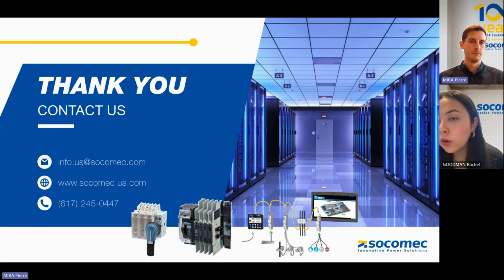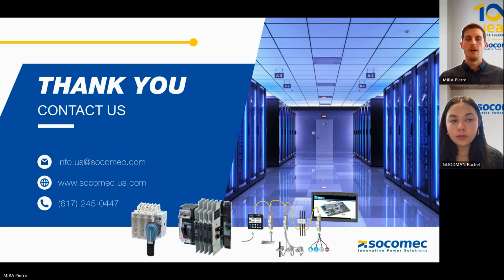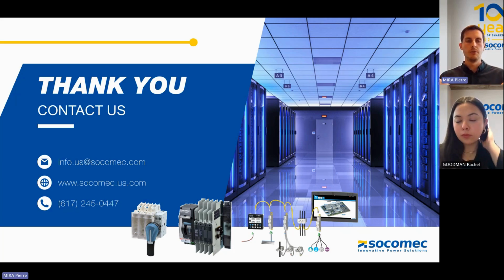Great. And we have one more question in the chat. Is an external bypass necessary? No. In a static transfer switch, bypasses are inside the system, meaning when we have a static transfer switch cabinet with a static transfer switch from Socomec inside, there is an embedded bypass at the cabinet level, meaning for each source 1 and source 2, we have bypass 1 and bypass 2.